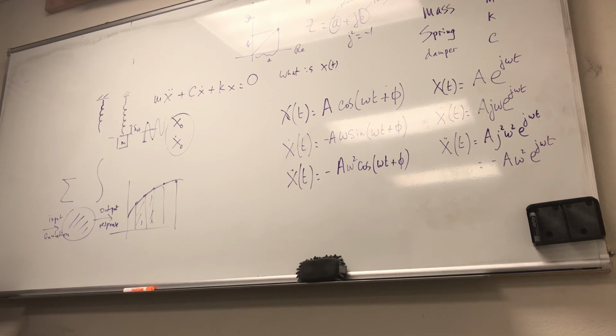So ideally you have the mass of the rider plus the mass of the motorcycle, supported on two ends. You're modeling this suspension, the strut here, so you have some K, some C, some K, some C, and then maybe some K here with the ground.